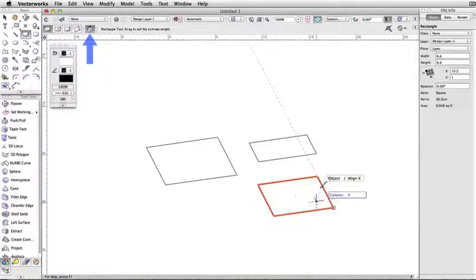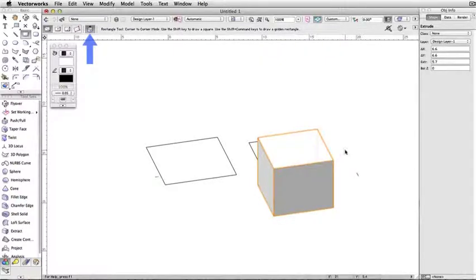With this mode enabled, immediately after you draw a rectangle, the push-pull tool will temporarily activate and allow you to click and drag on the face of your rectangle to create an extrude. Once you use this mode once, it will revert back to the standard rectangle tool.